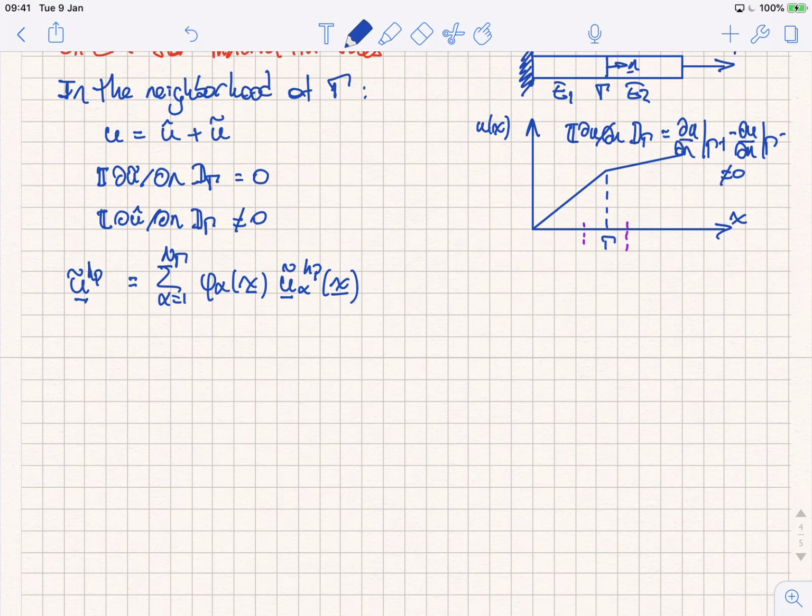What I'm doing here is I'm taking the partition of unity of my mesh, which is defined by these shape functions phi sub alpha. And every single one of those shape functions is multiplied by a u function that reproduces some behavior in that particular cloud or support. That is what this equation is saying. Okay? So let's explain a bit more that concept.